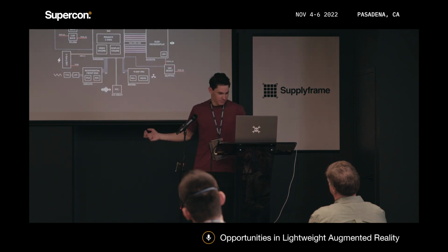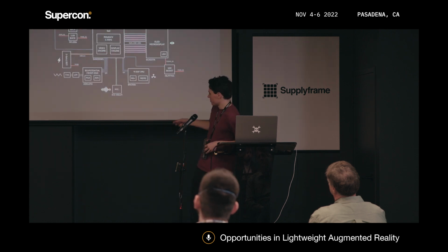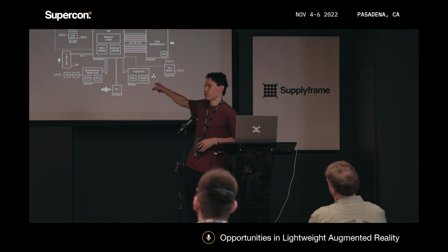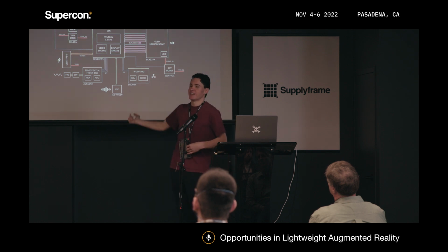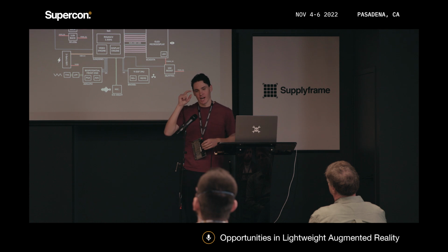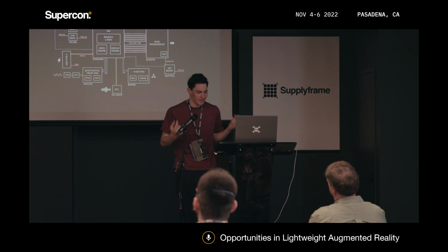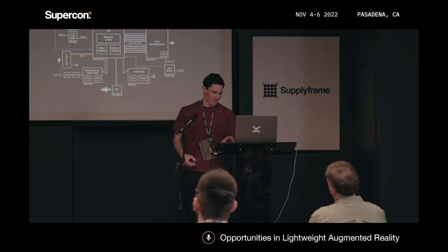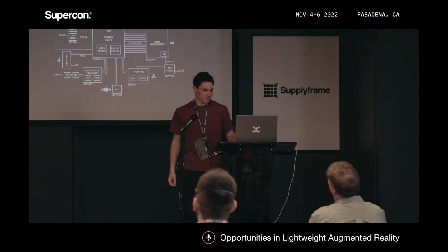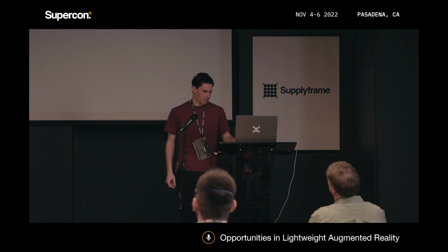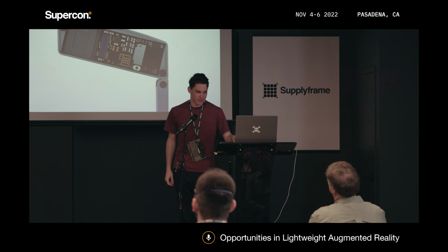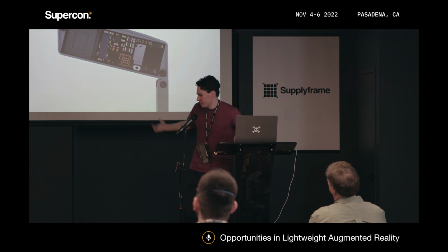It has the same sorts of peripherals. A few things have been added. Same IMU, microphone, Wi-Fi. Now I have a 2-channel biopotential front end, and the idea of that is potentially doing eye blink detection using electromyography. So there are a lot of interesting things that can be done there. And here are some graphics of how I imagined putting this in an enclosure.